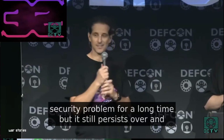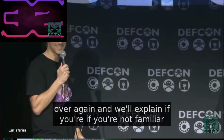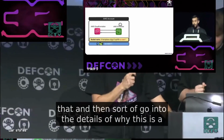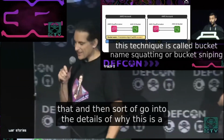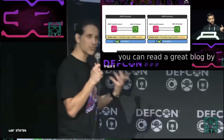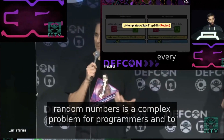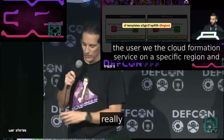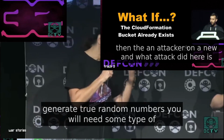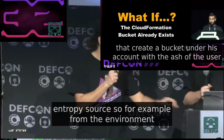Getting sound is actually not so challenging because our ears, we're pretty good at listening to just 1 kilohertz of sound. Although we can hear up to 20 kilohertz, with just 1 kilohertz, we can usually make out what someone is saying. The best I was able to get was 4 to 5 kilohertz of sound. And I found for keystroke extraction, I needed to get to 3 kilohertz. If I got to 2.5 kilohertz, I could not convert anything to keystrokes. If I got to 3 kilohertz, I could start converting to keystrokes.